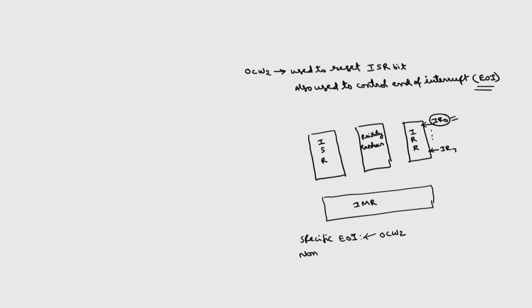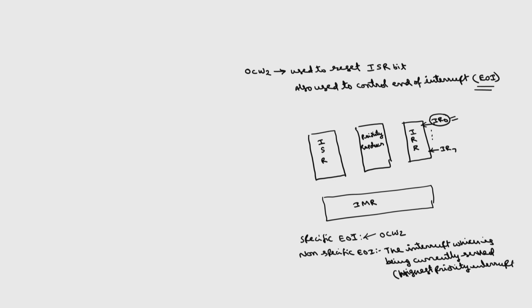Whereas in case of non-specific EOI, as the name implies, by default the interrupt which is currently being served, which is by default the highest priority interrupt, its corresponding bit of the ISR will be reset in case of non-specific EOI.